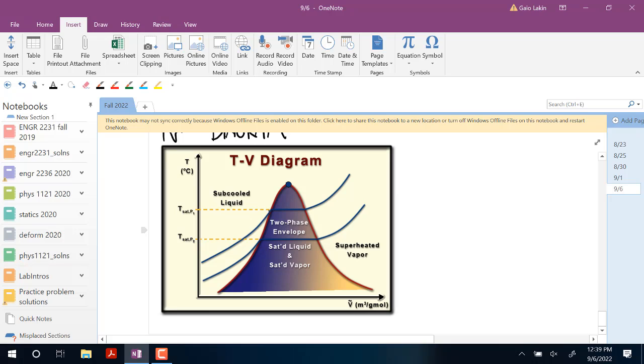And once you're at the boiling point, any internal energy you add just little by little switches this material over from liquid to vapor. It doesn't increase the temperature at all because saturated liquid and saturated vapor have the same temperature. Okay, and so as you keep adding energy, this is the one region, and also the phase change between solid and liquid.